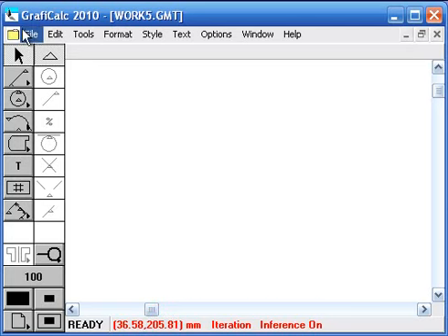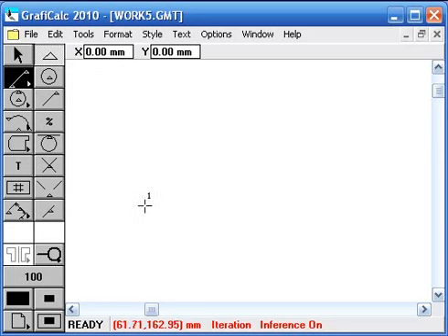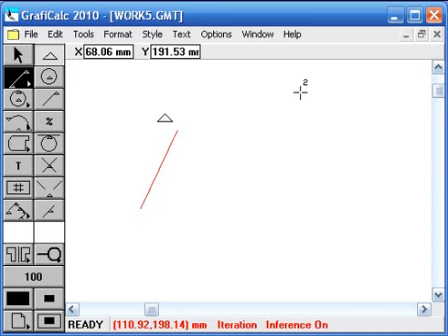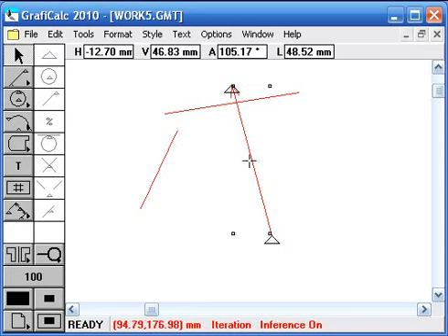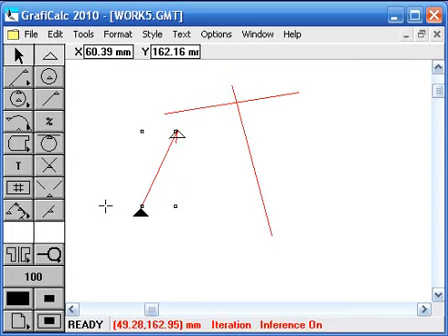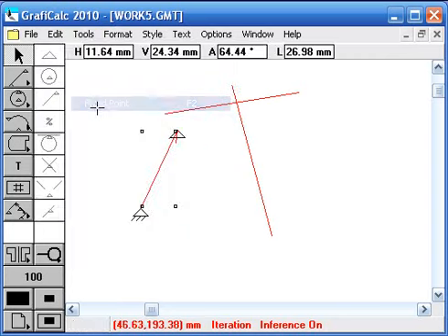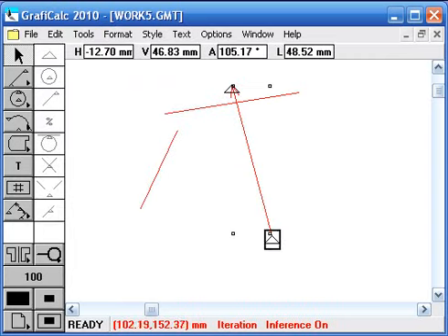So to create a four-bar link, it's pretty straightforward. You start with a driver, then you just sketch the connecting link, and then this is what's going to be driven. So I always keep the polarity, so I start these two links from the mount points or the swivel points, so I will just fix it here, and I will fix this here.